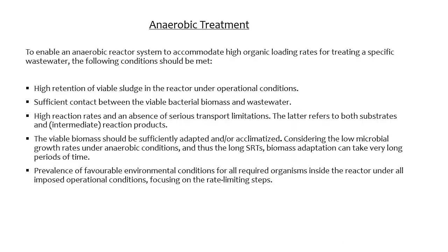To enable an anaerobic reactor system to accommodate high organic loading rates for treating a specific wastewater, the following conditions should be met. High retention of viable sludge in the reactor under operational conditions. Sufficient contact between the viable bacterial biomass and wastewater. High reaction rates and an absence of serious transport limitations. The latter refers to both substrates and intermediate reaction products.